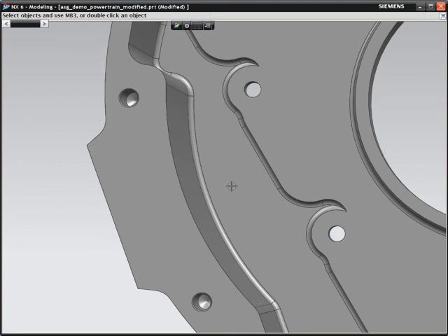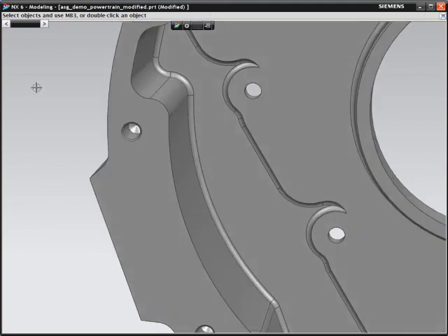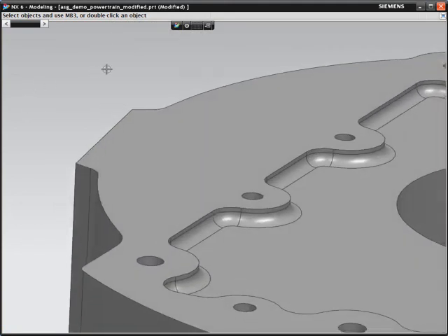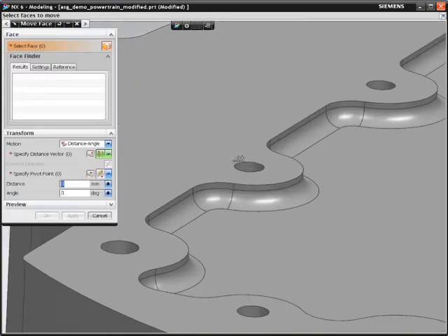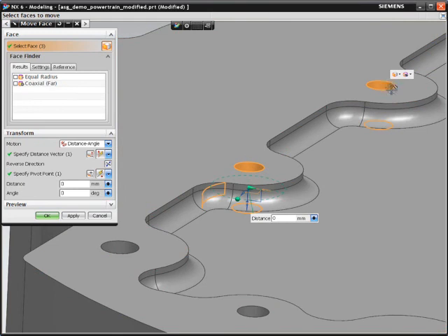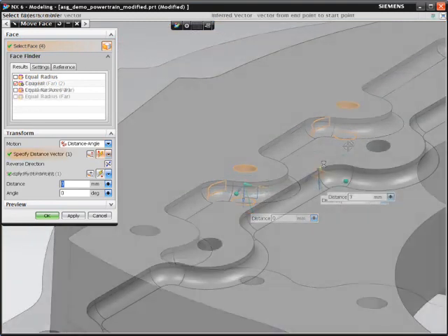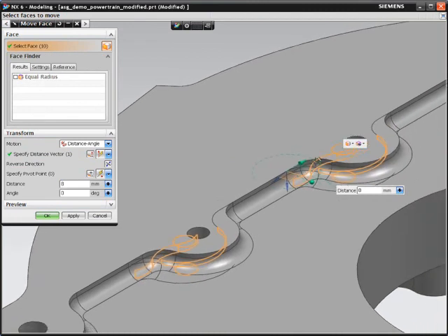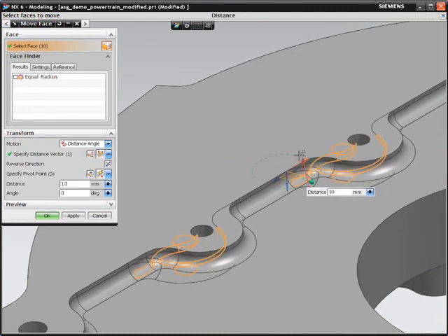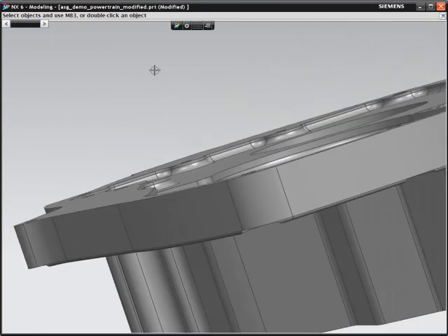If you had time, you could go back to the part history to determine how to make what appears to be simple changes. Stepping the model back, you decide to use a more streamlined process made possible by Design Freedom and which still works within the parametric approach. Design Freedom lets you select intelligently, like coaxial relationships with active selection, a key component of synchronous technology, while still being able to add individual geometry during the edit.